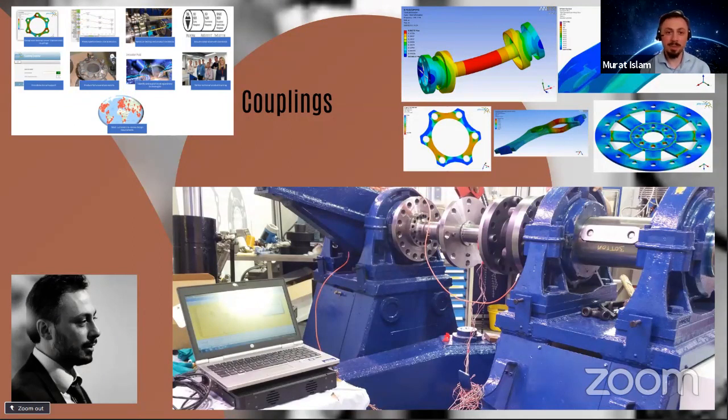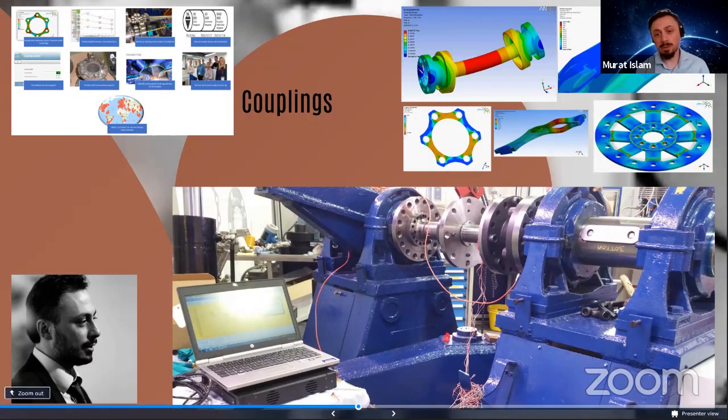There are many other properties we can be testing. You can look at material surface hardness. If that hardness is too much for another component next to it, it will actually scratch it, it will wear it very fast. They may dig into each other literally, so you need to be careful selecting hard materials and using them together. And as you can see here, at the right-hand side bottom, the actual static torque test rig